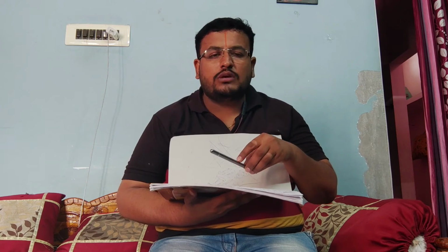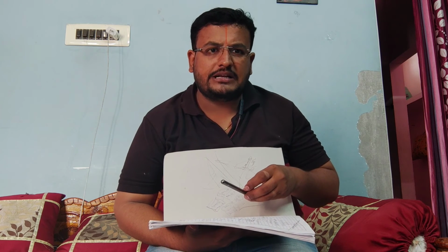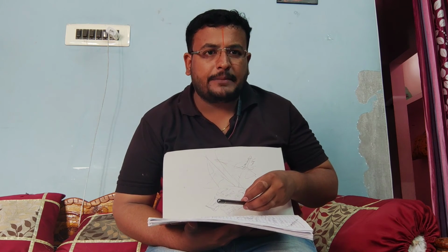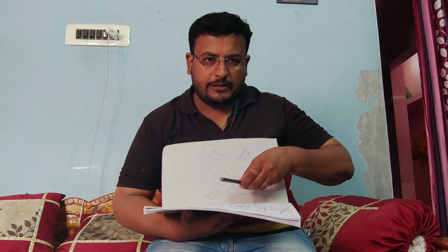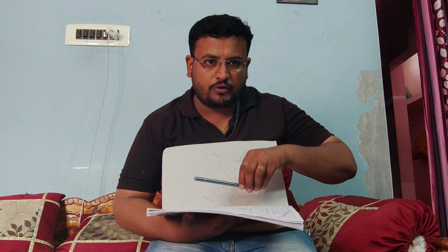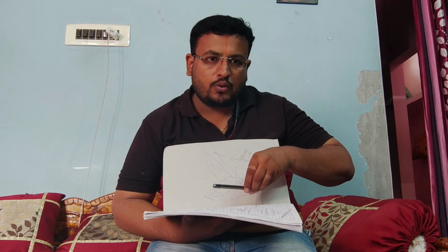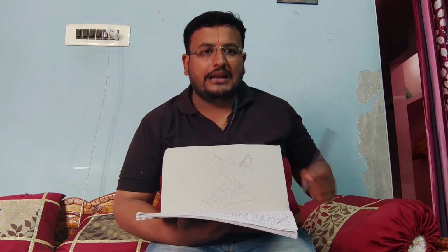As we know, if the line is inclined to VP, always VP inclination can be seen from which view? Top view. Always VP inclination can be seen from top view. That means on which plane? On horizontal plane. That means we have to tilt this line in making inclination with VP. That means in the top view, you have to rotate the fake view which you had drawn previously up to the given angle in the question, and if you project the same to the front view, you can get the reduced length.